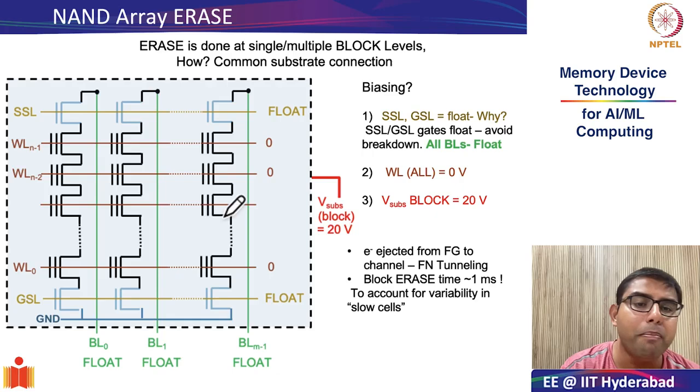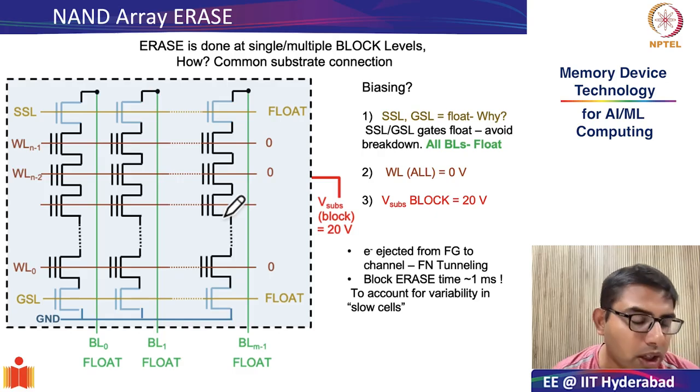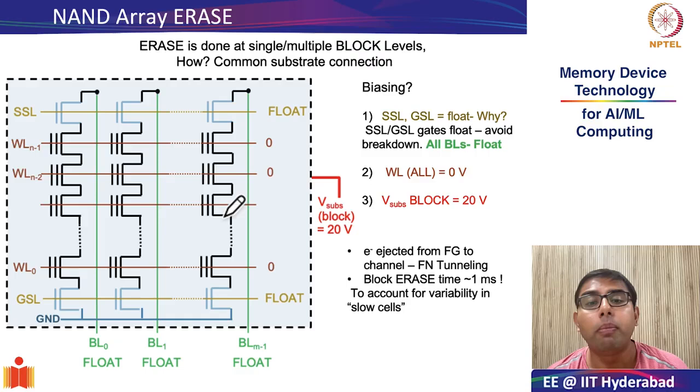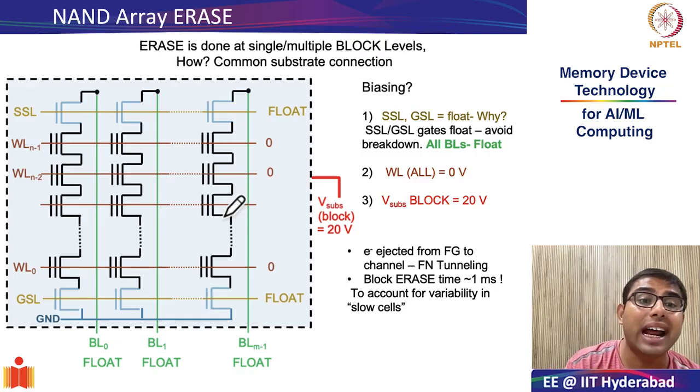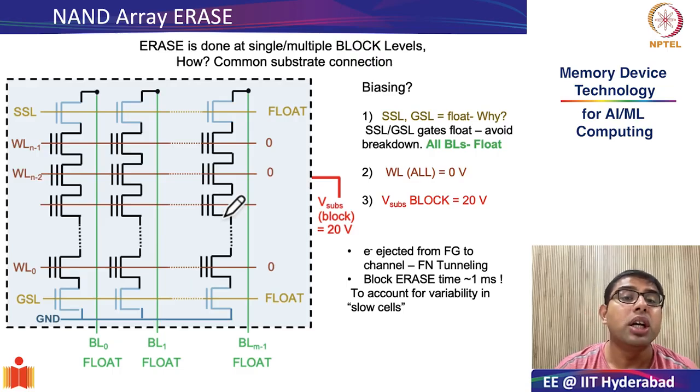Now, another very important thing to emphasize is, remember that block erase times are generally significantly larger compared to read times and program times, which happen at the page level. So generally block erase times are on the order of 1 millisecond.